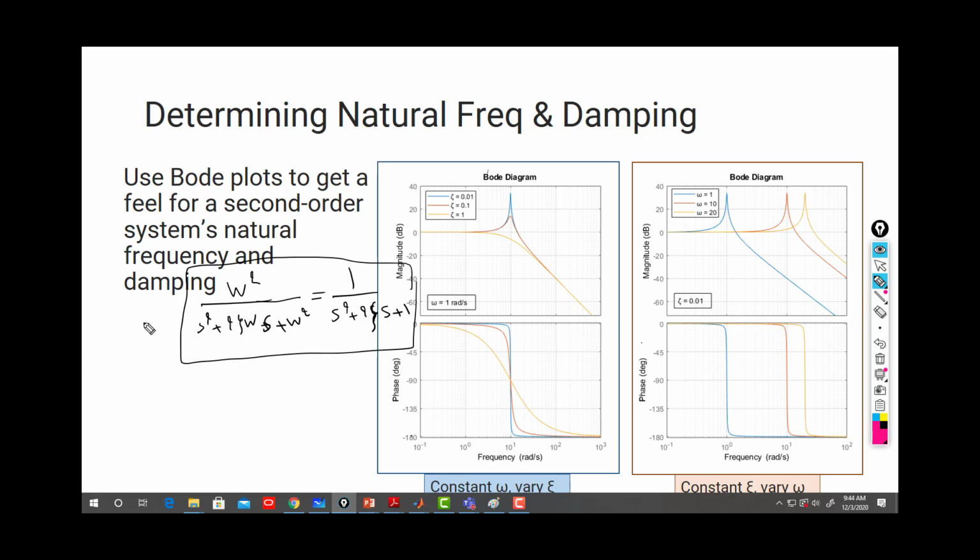So my system has 3 zetas, zeta 1, zeta 2, zeta 3, and for each system, so I have 3 systems, I'm putting it in a frequency analyzer where I'm injecting an input sinusoid with a varying frequency within a frequency band, let's say from 0 to 500 hertz, and I'm looking at the output, how the output will behave for different frequencies, and I'm recording.